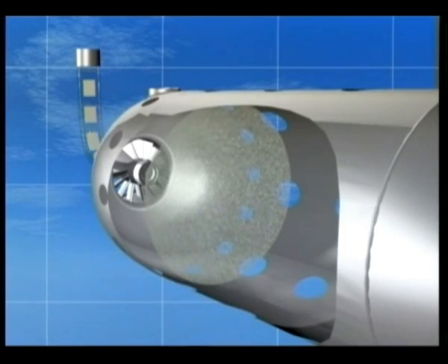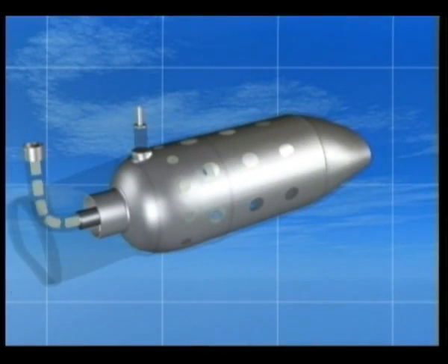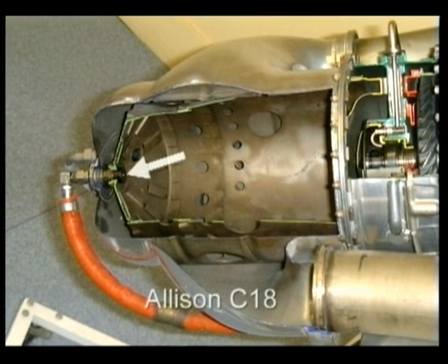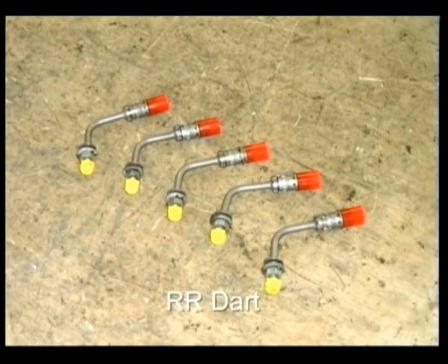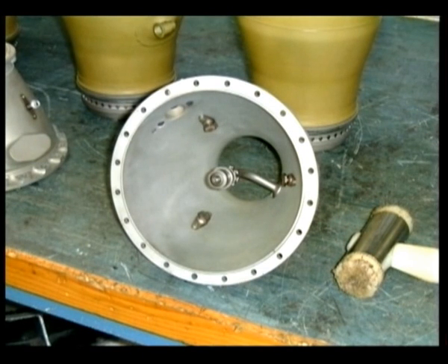The fuel is finely divided, or atomized, into a turbulent stream of air, the mixture then being vaporized and burnt. Because fuel drops burn on their outer surface, they must be small enough to ensure that combustion is completed within the combustion zone. Forcing fuel under high pressure through very fine holes within the spray nozzle ensures small droplets. The job of the burner is to inject fuel in a readily ignitable form into the flame tubes of the combustion chambers. There are a number of different types of burners in current use.